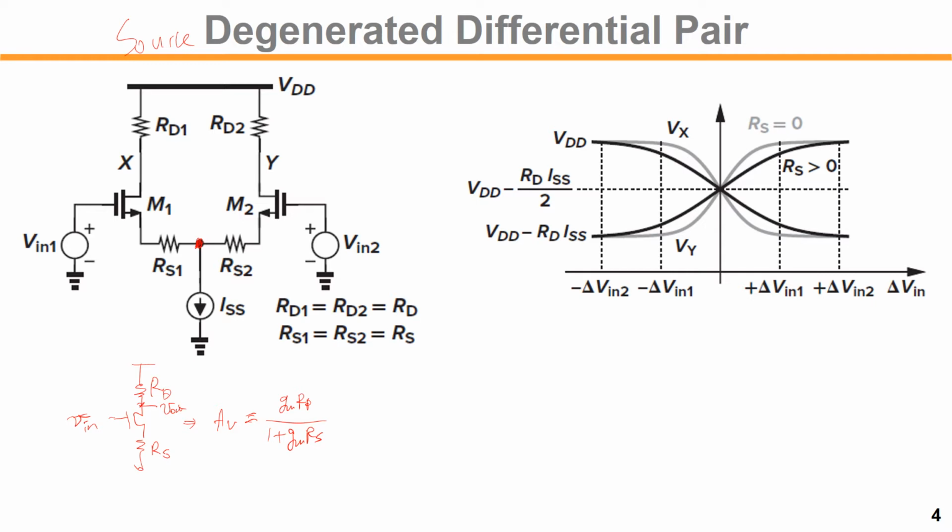So this is for a small input variation up and down on both terminals by the same amount, which will create the differential current ID. So this center node would not change, the voltage would not change, so it would be AC ground. So you can find the small signal equivalent model like this, a single-ended version of the equivalent model, so we can find the gain similarly.